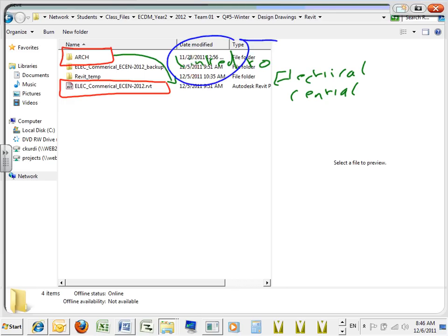The linking is equivalent to XREFing. It's already done for you. In CAD, instead of one XREF, we XREFed every layout: the site, the garage, and the upper and lower levels. In Revit, you only XREF or link one file. This is a major difference between CAD and Revit. In Revit, you link only one 3D model, and from this file you can have different views.